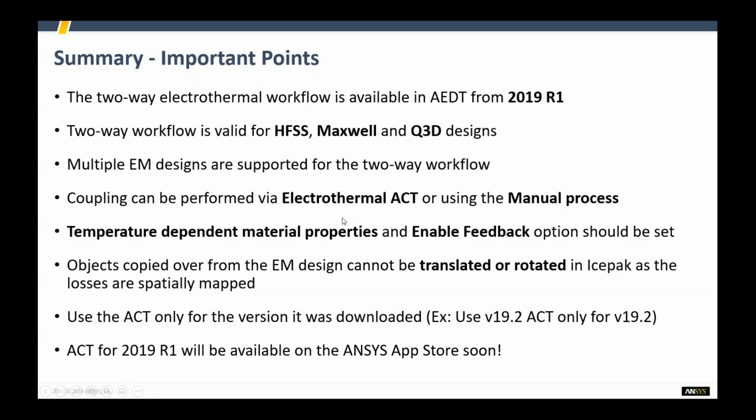It probably doesn't solve at the same time, but you can ask them to solve by just having a single click, and they're solved sequentially. Coupling can be performed via the ACT way or the manual process. Temperature-dependent material properties and the enable feedback options have to be turned on.